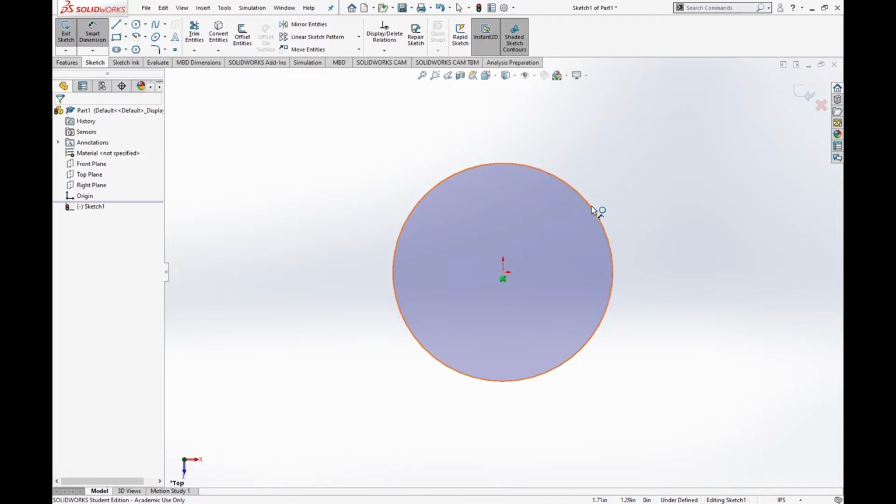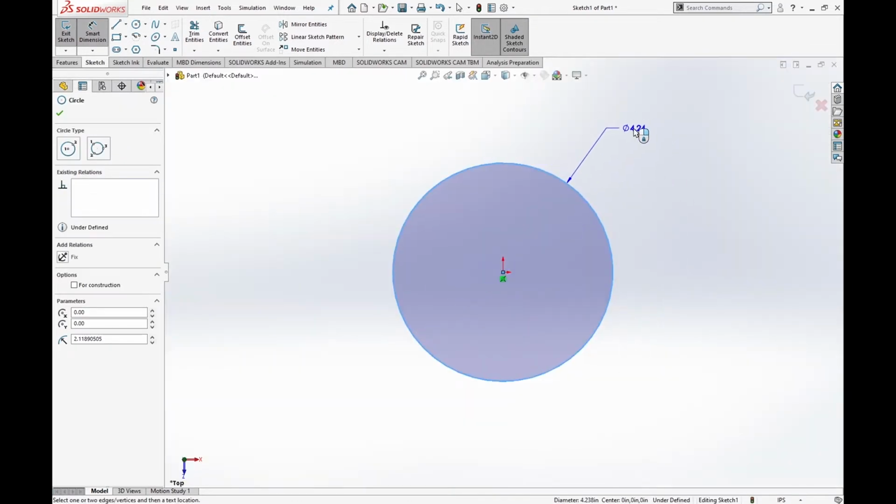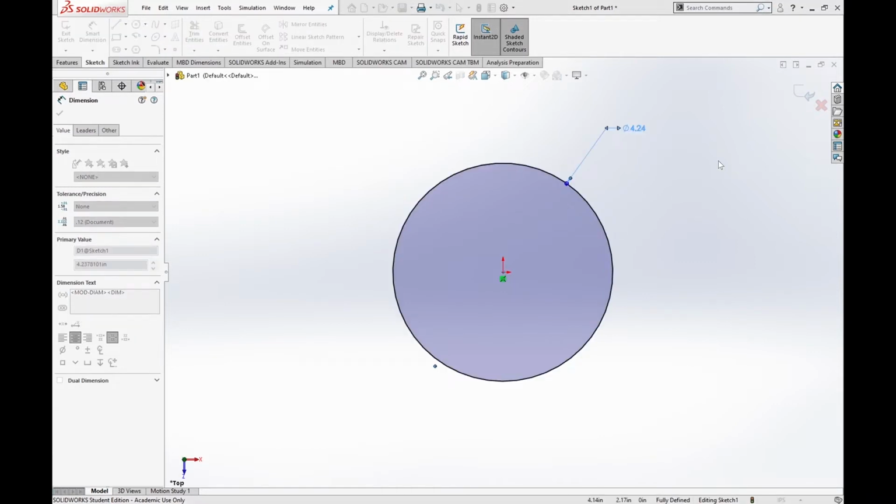Our rule of thumb, and the way that we have done it in the past, is we add 1/8 of an inch all the way around our gears as clearance from the gear when it rotates. If I know that my OD for my gear is 4.2, and I want to leave an 1/8 inch clearance, I need to add an 1/8 inch clearance on the top part and also on the bottom. So that brings it up to 1/4 inch all the way around.